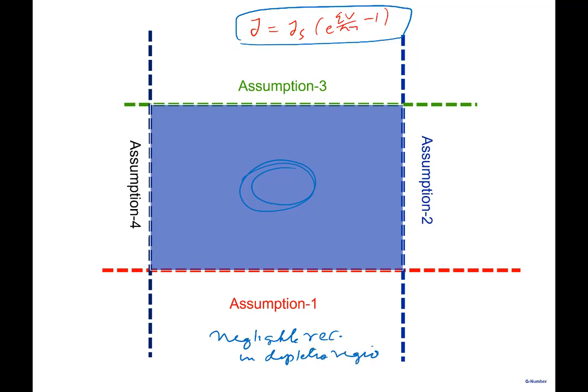Another one? Very thick PN regions. Then? Electric field is 0 in the bulk. So what it's saying is negligible drop in the bulk. Or anything else? The minority carrier current is diffusive, and also low level injection. Both low level injection.